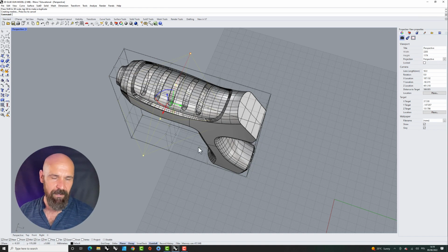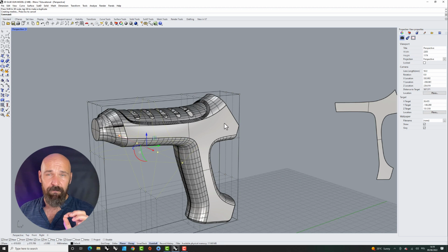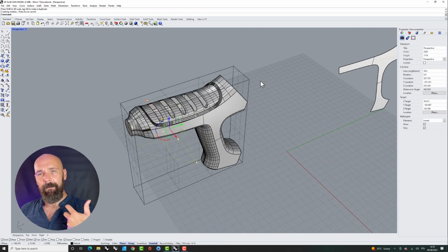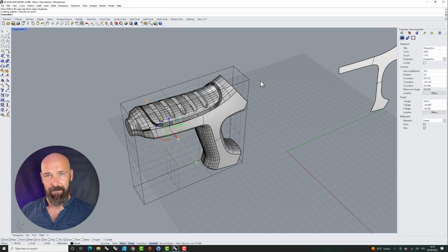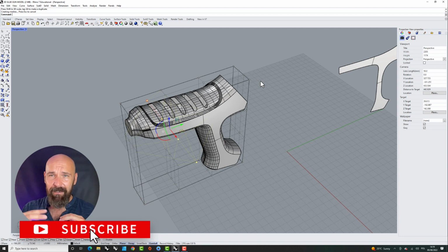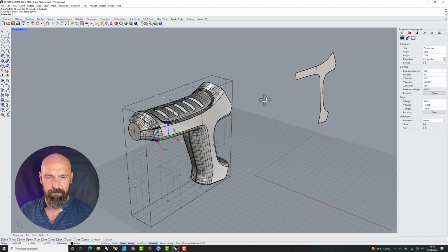So the same here. But you need to be very careful during that process, because if you are making your design for market implementation, you need to remember about the draft angle. Otherwise you can destroy the form in terms of injection molding. Be careful about that. But anyway, at the designing stage, that's fair enough. You can play with this.